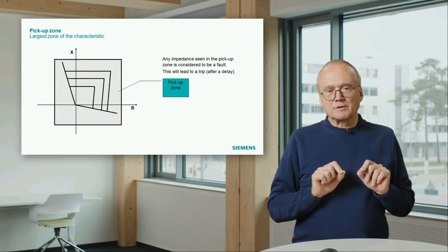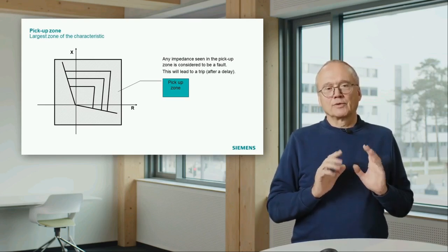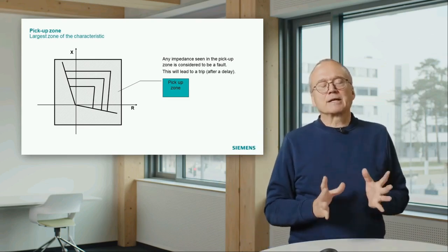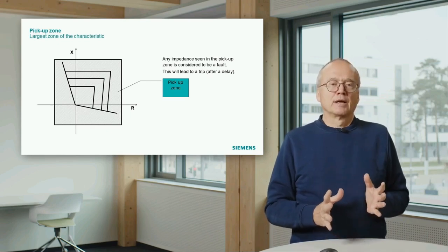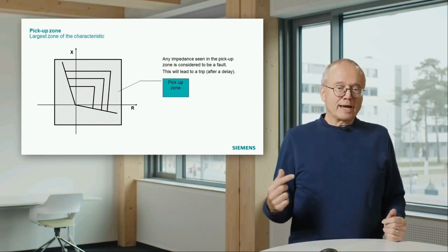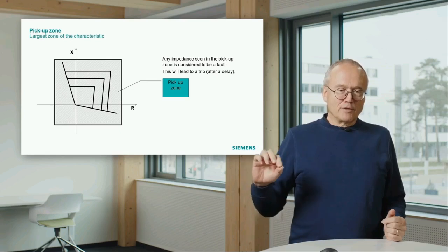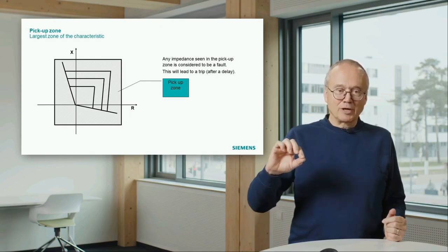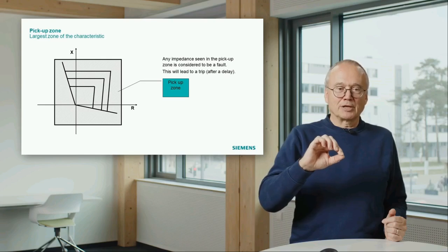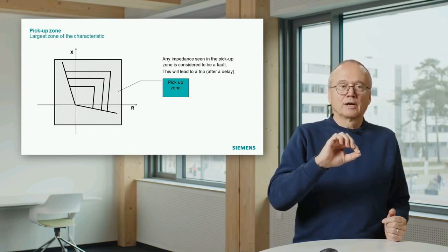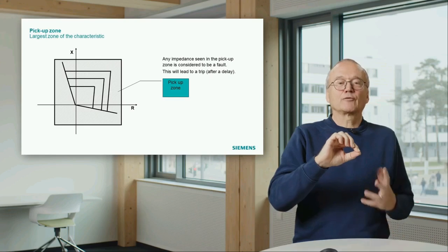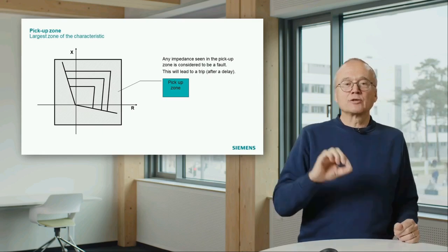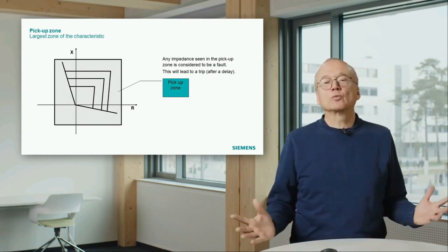And this pickup zone requires particular attention, because you must be careful to define the size of this pickup zone. And this pickup zone defines two things. You should be aware of the impedance measurement with heavy load: remember, with heavy load the measured impedance is approaching our characteristic. And if you are in a critical situation, you suddenly may move into the characteristic and then you will trip.